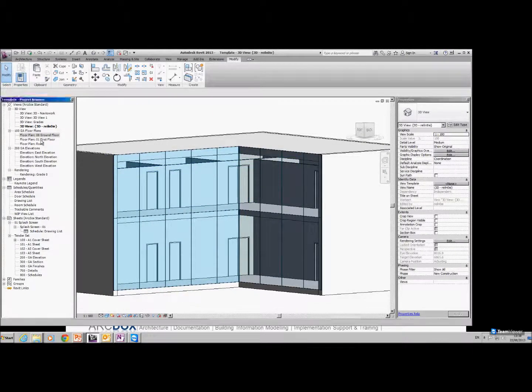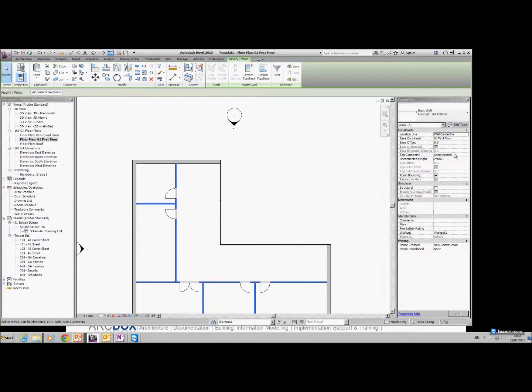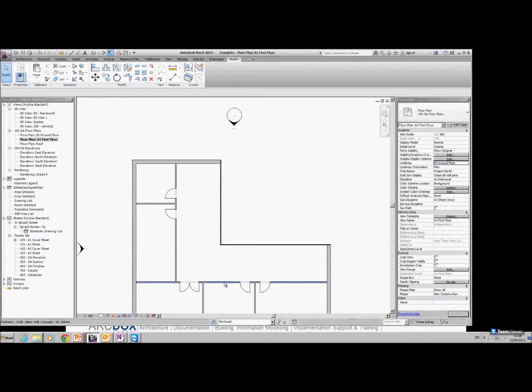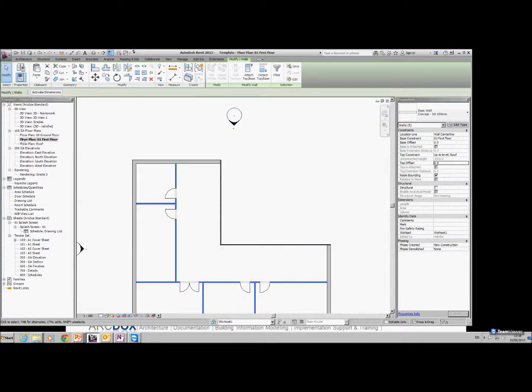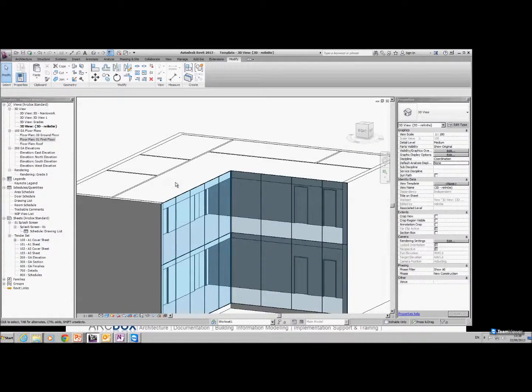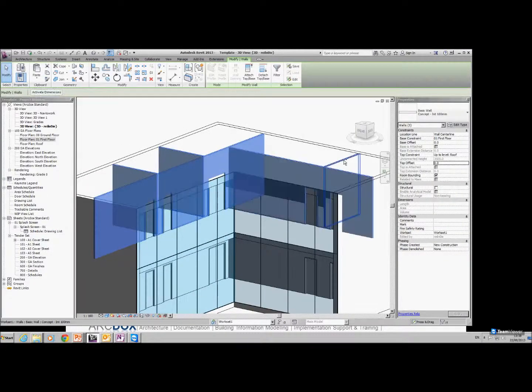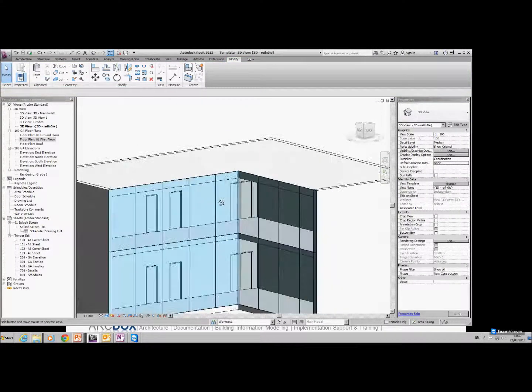The same here. I'm going to go into my first floor, instances visible in view, this up to the roof, top offset. Actually, no, I don't want to bring them up to the roof. Select, highlight, select all in view. 3D, are they all? Nope. These here, actually. Patch 2. There. So they're all fitting now. And there's no stairs there.